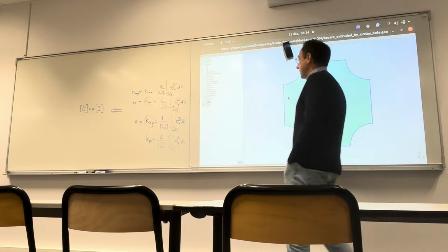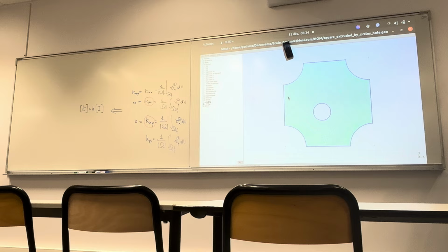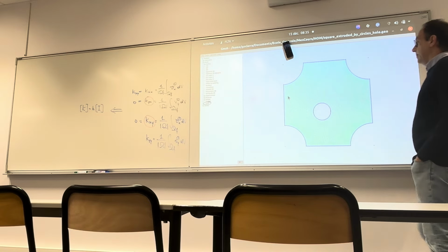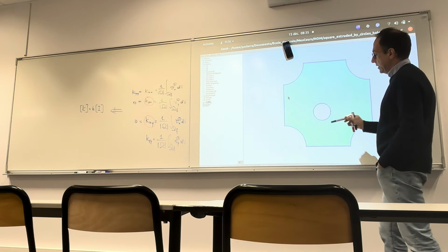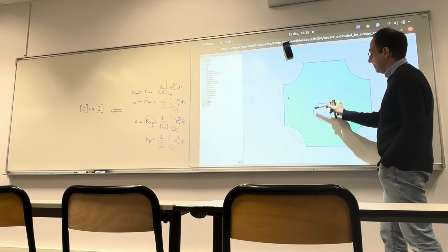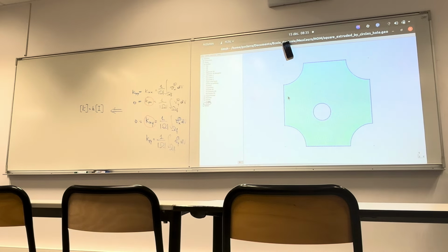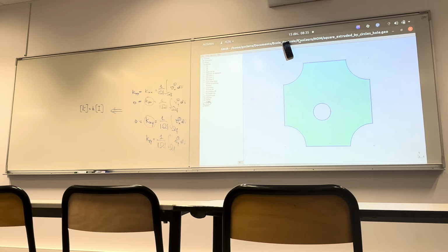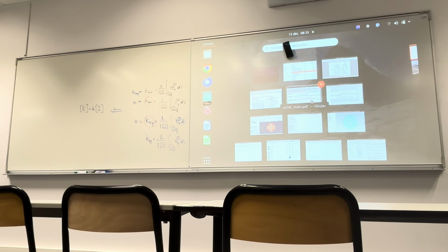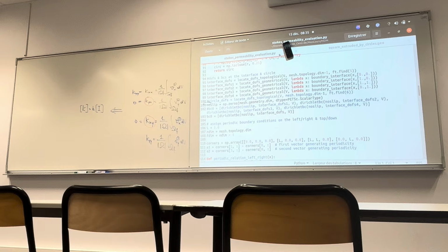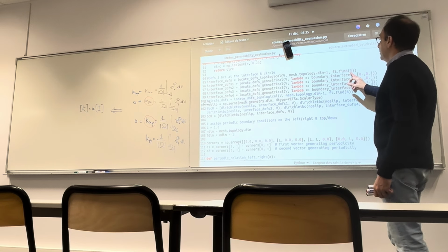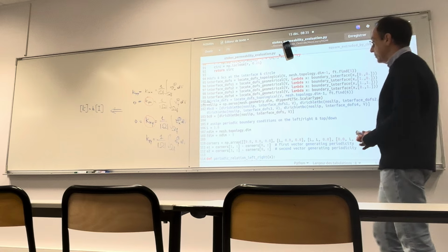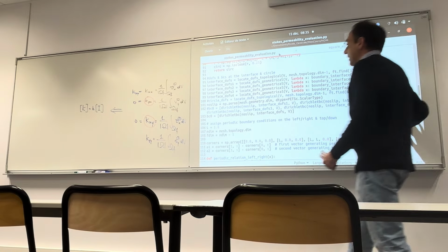And so with this new MSH file, normally, if you have just included the circle into the subdomain labeled as 5, you don't need to change the Python script anymore, because in the Python script you just look for the domain labeled as 5 and attribute to it a vanishing Dirichlet boundary condition for the velocity. Everything else remains the same.